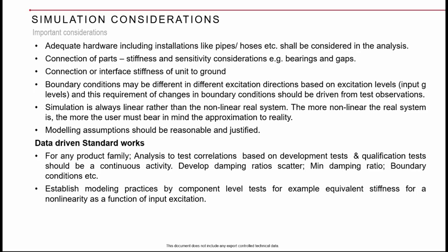And one important aspect I would like to emphasize, for any simulation considerations or when you are developing standard work within your groups, is that your standard work should be data driven. For any product family, you should have some considerations or recommendations in your standard work, product family wise or feature wise. Like features, when I say particular joints, for example, how you should model them, whether there should be any relation with respect to the excitation levels, whether there should be any relation of stiffness versus certain forces or stiffness versus certain excitation levels.